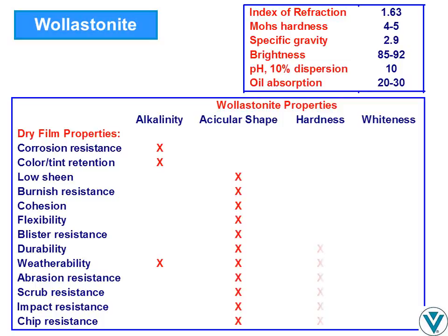Wollastonite is used in epoxy powder coatings because its low binder demand promotes smooth flow, water resistance, improved adhesion, and good chip resistance. Coarser, more acicular grades are used in primers because they provide a micro-textured surface with good tooth for finish coats. In decorative powder coatings, 10 micron and 400 mesh wollastonites are used to provide a smooth satin finish.